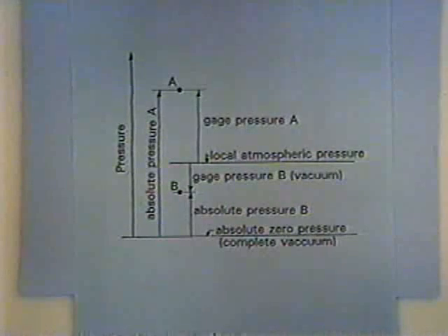Let's say we're on the suction side of a pump, for example, and that would be an example where you could get a pressure which is less than atmospheric pressure. We'll look at a problem next week dealing with pumps and the fact that you can get the pump so high and the velocity so high that you can reduce the pressure on the downstream suction side of the pump to something near absolute zero, and we can talk next week about what that implies.